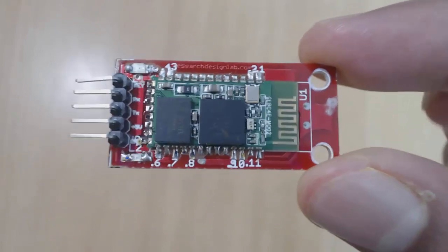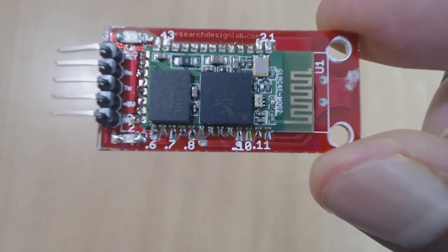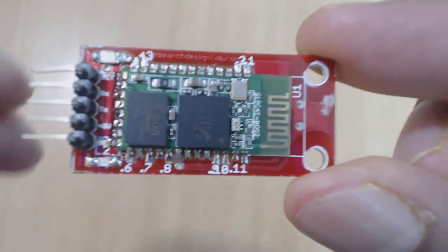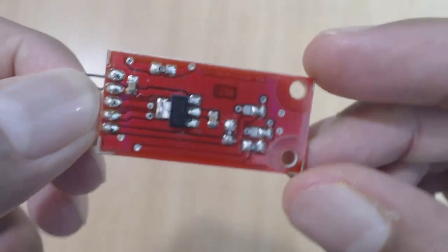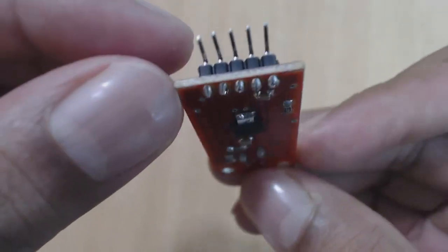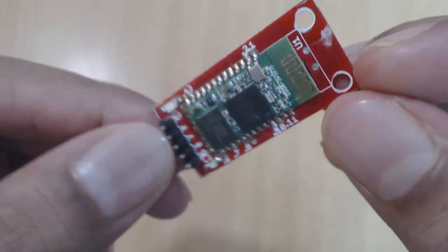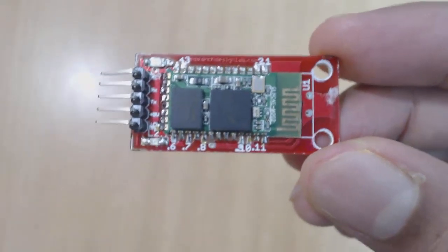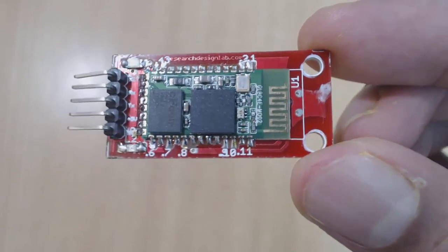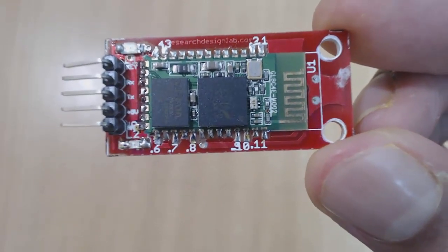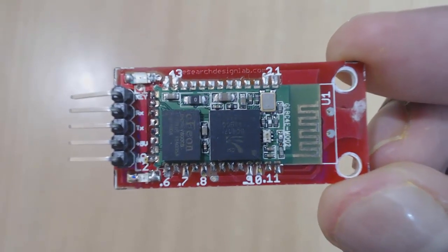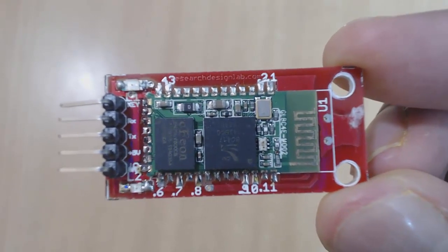One will be either 5 volt or 3 volt and one will be a ground pin, and then other 2 will be TX and RX pin for transmitting and receiving. And then if some extra pins it has, then those are for some other purposes. So it will not impact anything that we will do in this tutorial. Hence, you don't have to get exactly this kind of looking module. If you have other kind, that will also work.